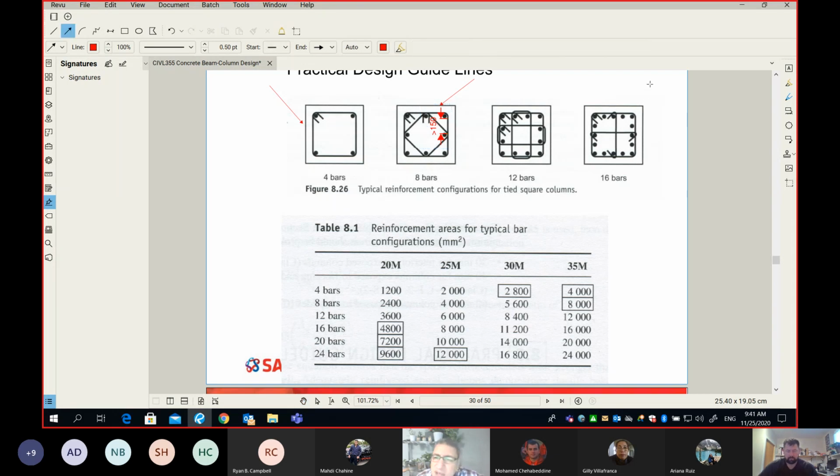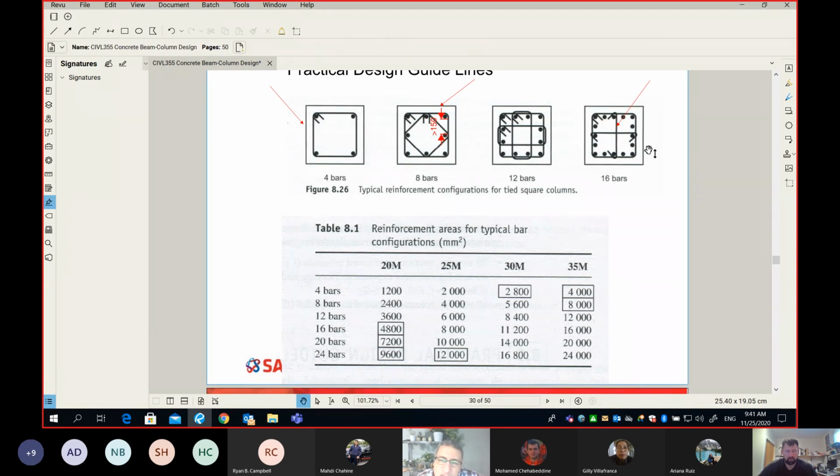Really, what I don't like is this one. To be honest, I am not really a big fan of those. Anybody who has experience will tell me I agree. You know why I hate this configuration here? Why don't you like it, Tahir? I've seen them a few times, but not very often. Those are, look, Gord, those are very, very weak. They always fall down when you pour your concrete. Always. This here is called a hairpin. Okay, it's very weak and very hard.